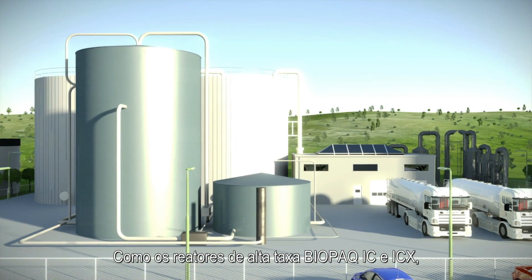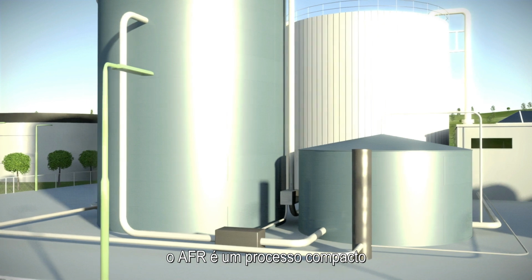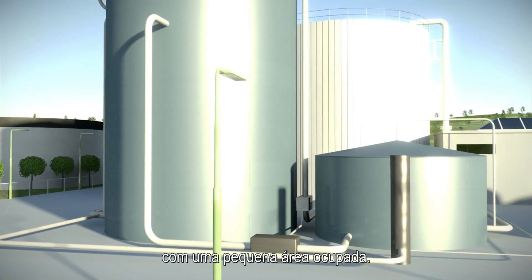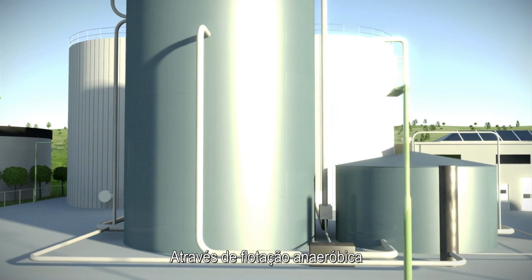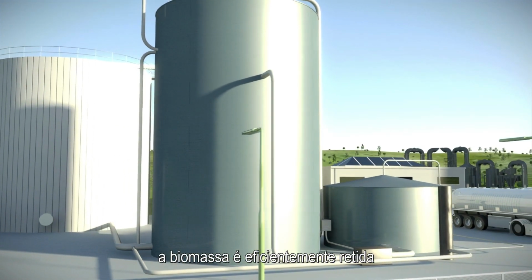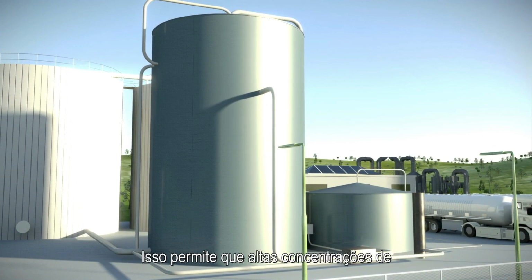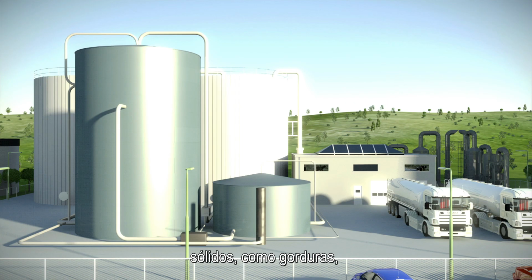Like the BIOPAQ high-rate reactors, IC and ICX, the AFR is a compact process with a small footprint. By means of anaerobic flotation, the biomass is efficiently retained, resulting in long biomass retention times. This allows high concentrations of solids such as fats to be converted efficiently.